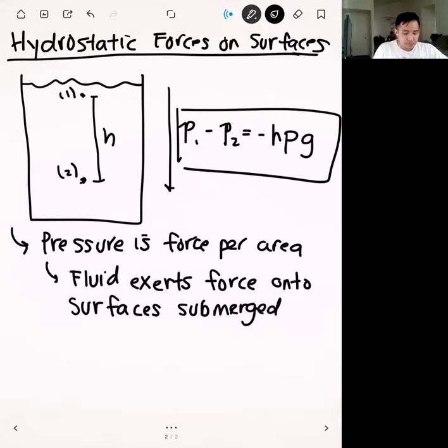And so the whole idea with this unit was to basically, you can think of it as almost like an extension of your typical statics class or strength of materials, to see, if we submerge surfaces into a fluid, what are the magnitudes of the forces and what are the locations of the forces.